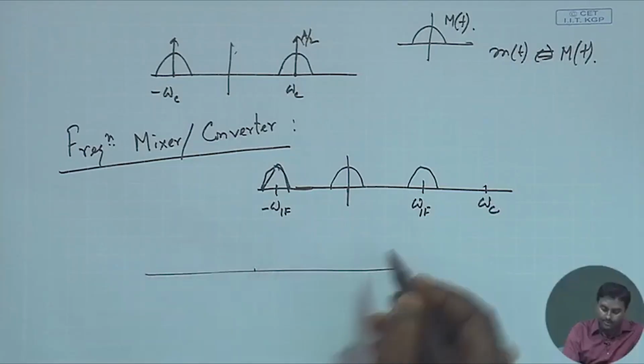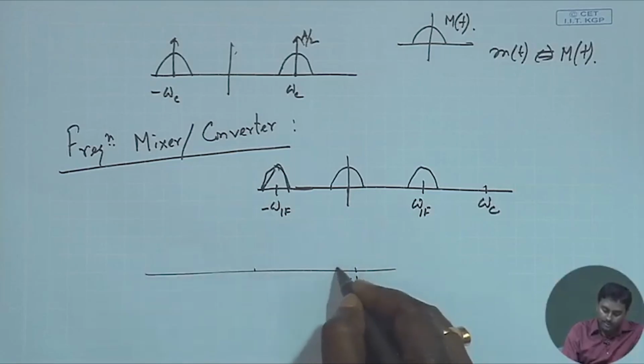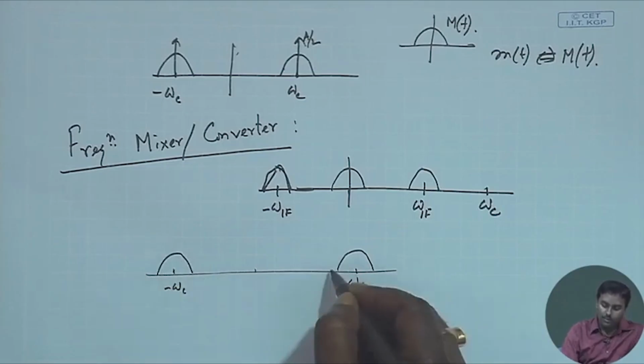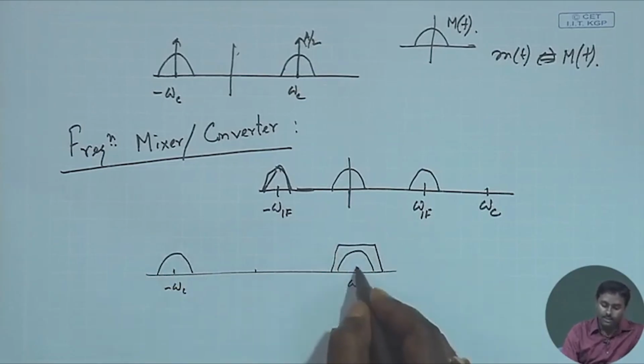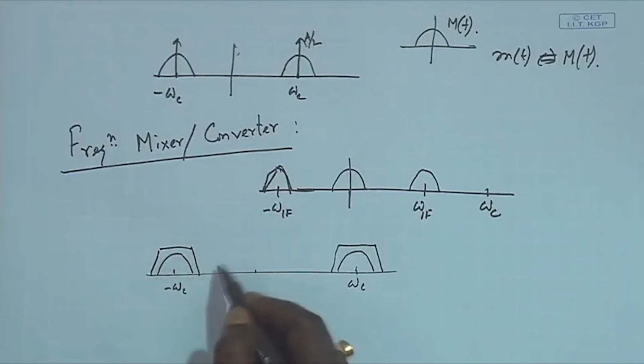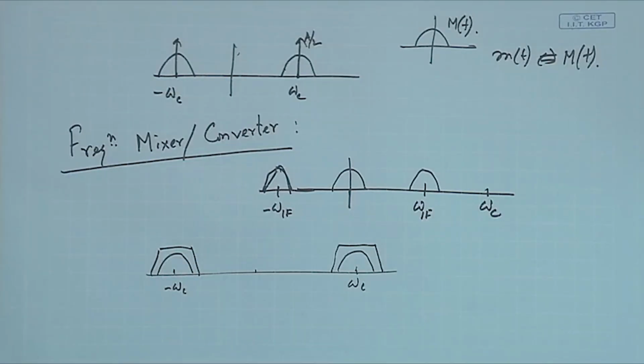that after receiving whatever signal I receive. So, suppose my modulated signal is coming. So, this is centered around omega c, minus omega c. I put a band pass filter centered around omega c, and the bandwidth should be greater than the 2b value, right. We have discussed about the bandwidth for a modulated signal. Okay, so, I will get just this one. If there are some spurious things in other frequencies, that will be all rejected. I will just get my signal.